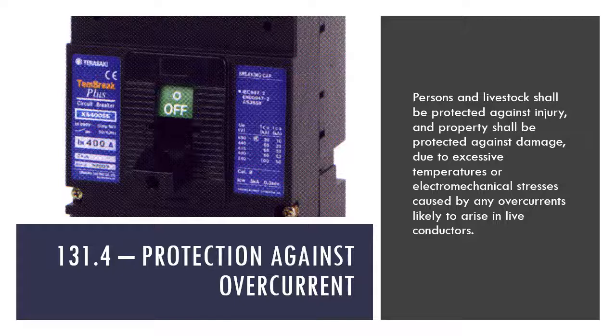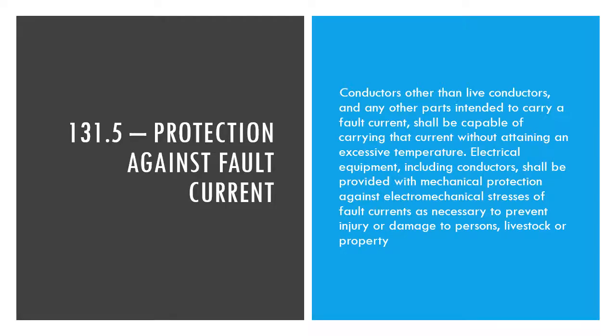And we've just mentioned previously about limiting the amount of current. So we look at protection against overcurrent in 131.4, where persons and livestock should be protected against any injury, and property shall be protected against damage due to excessive temperatures or electromechanical stresses caused by any overcurrents likely to arise.